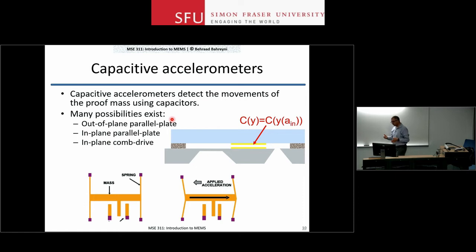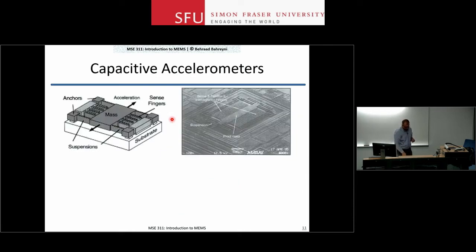But as we saw before, usually the capacitance you get from two electrodes is small, so we use a comb in most situations in order to increase the capacitance, or the dC/dx factor that we saw was important in actuation and also sensing for electrostatic devices. In some cases, you may want your mechanical device to work based on torsion. So what you can do is make a capacitive device, and if this plate is tilting in and out of plane, you can measure a change in capacitance.